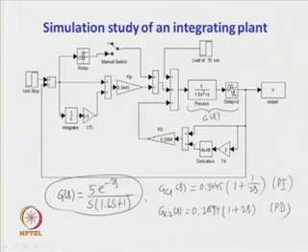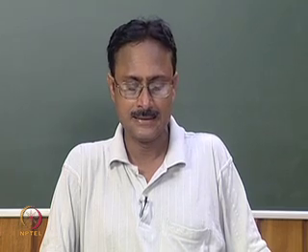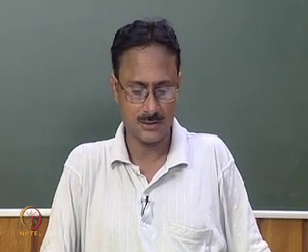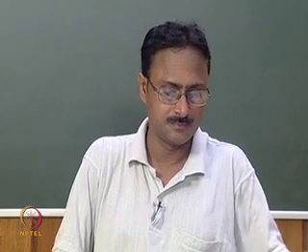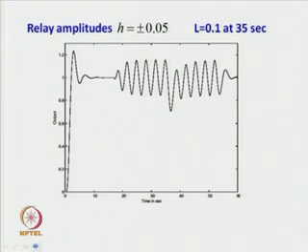With this PI PD controller, it is possible to get satisfactory time response from the closed loop system. Now, as far as auto tuning is concerned, the relay is switched on and then we get limit cycle output signal. So, when the relay is switched on, even in the presence of a static load disturbance which occurs at time t equal to 35 seconds, we get a relay output signal of this form.